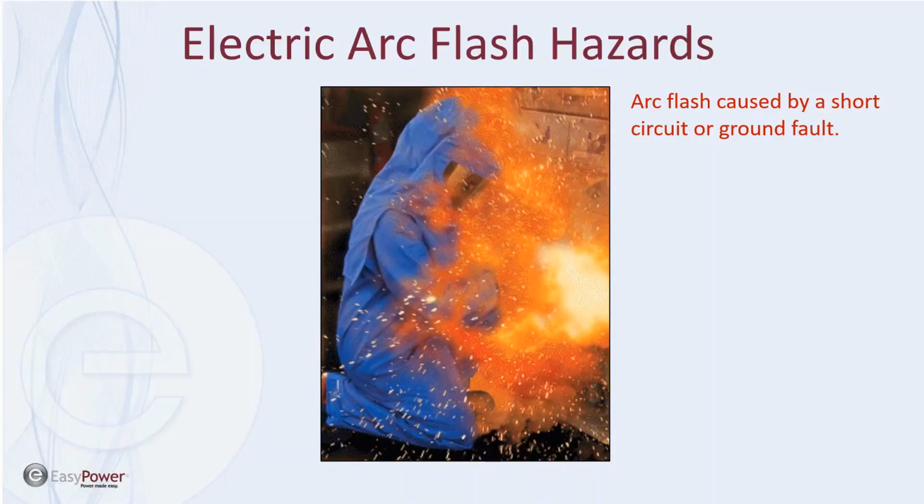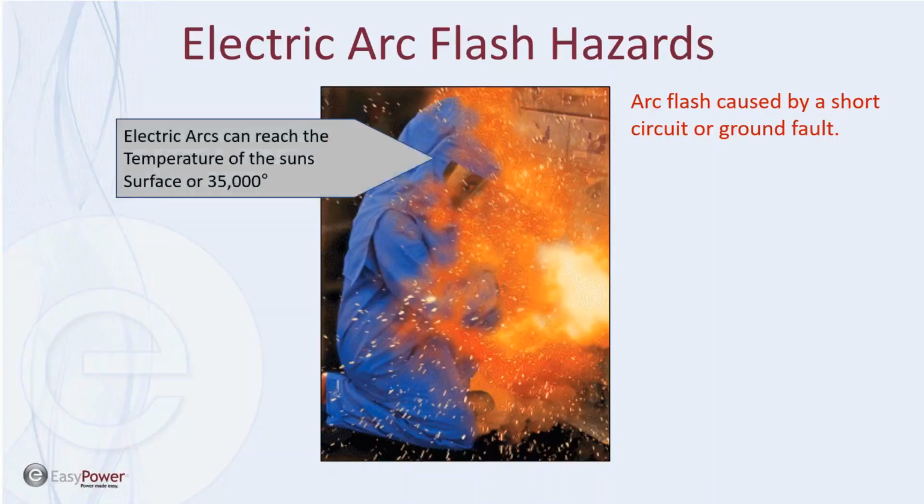So generally, it could be tools or it could be failure of equipment. Whenever you have moving parts within an equipment and you move those parts within the exposed energized parts, you have the risk of causing a contact, which will cause a ground fault or a short circuit. And that's the kind of thing that we have to take care of based on maintenance. And so that's important. So a little bit more on arc flash stuff.